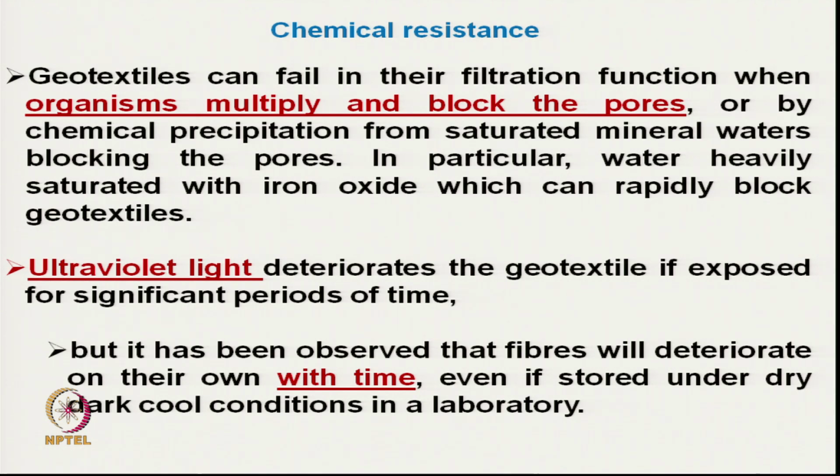Ultimately they are reducing the filtration or drainage performance. Also, when the water is saturated with iron oxide, it may deposit inside the structure and block the geotextiles.